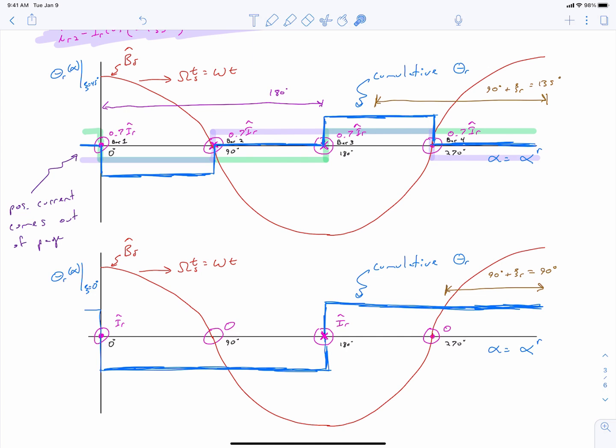And so I want to just point out at this instance that this 4-slot rotor is not a practical induction motor design. Don't design an induction motor with 4 slots. It's far too low of a rotor bar count to give you a reasonable design. In fact, in this whole example here, we're not going to look at rotor bar counts that would be representative of an actual induction motor, because it would take too many bars.